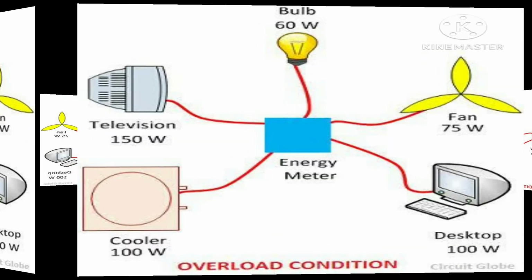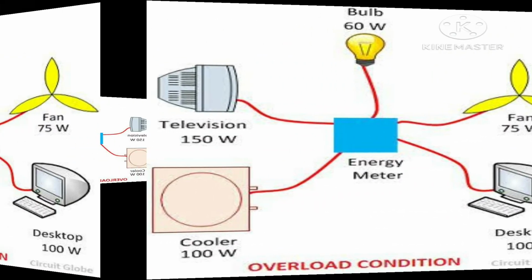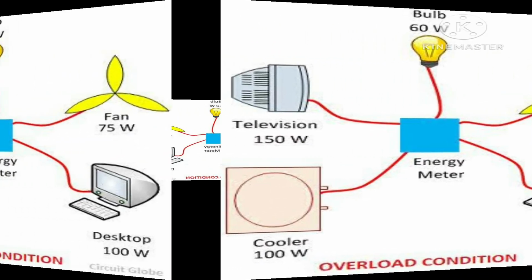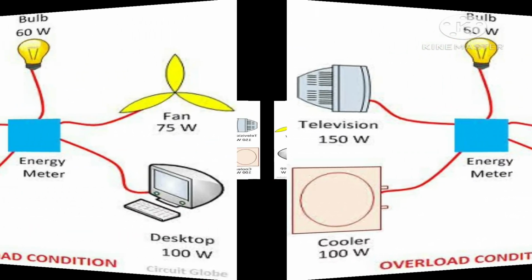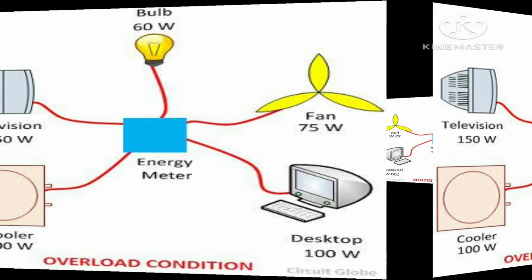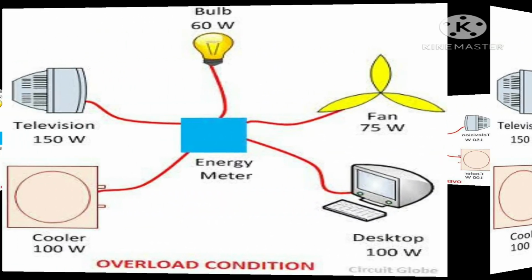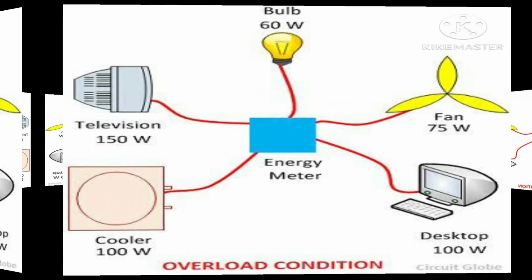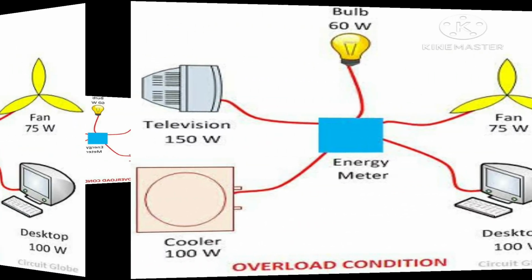The second one is overloading. The overheating of electrical wiring in any circuit due to the flow of large current through it is called overloading of the electrical circuit. Excessive overloading for a long period may lead to electric fires.